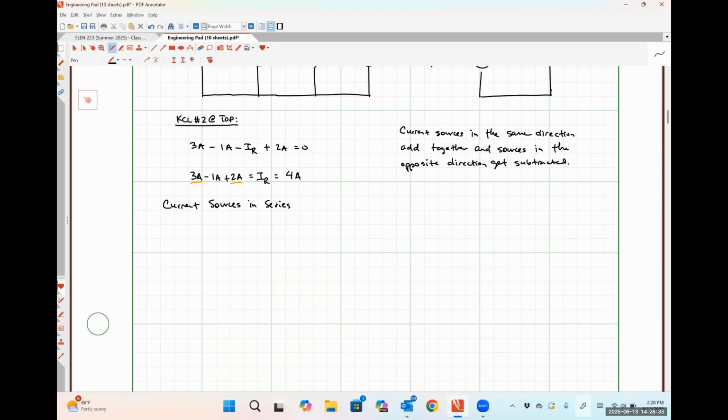The only example that I can think of where you see current sources in series is specific transistor circuits where the transistors are being used as non-ideal current sources and are combined in what's called a cascode configuration. So unless you are an electrical engineer going into electronics design or integrated circuit design, you will pretty much never see current sources connected in series, for what it's worth.